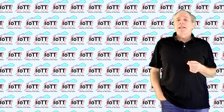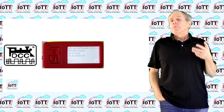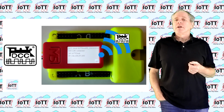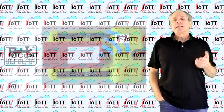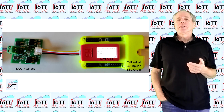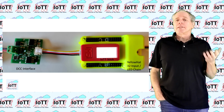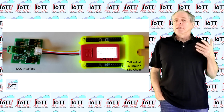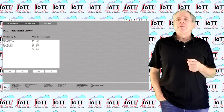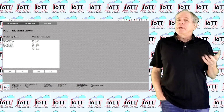The DCC functionality is straightforward. The IoTT Stick can receive DCC commands, process them in the function head, and optionally forward them to other nodes via Wi-Fi. To receive DCC commands, the stick implements two methods. The first is connecting the IoTT Stick to the track using a DCC interface and decode the commands in real time. After decoding, the incoming commands are displayed in the DCC viewer, which is automatically available whenever DCC commands are received. The screen is split in two sections.